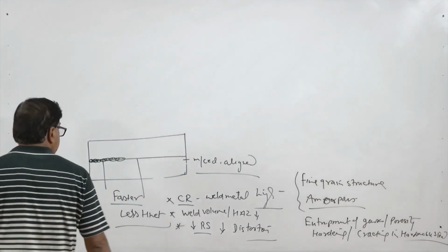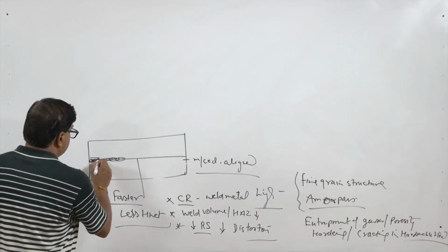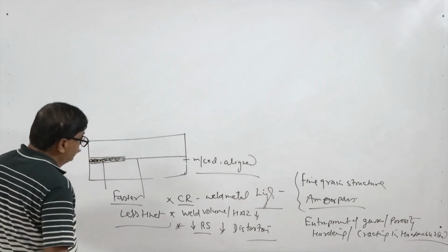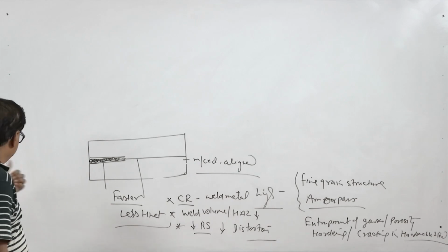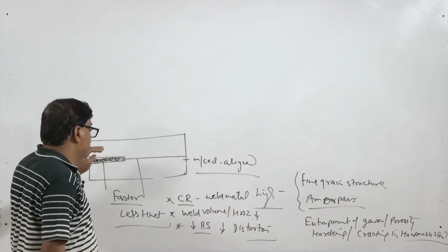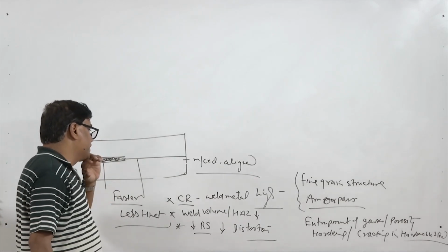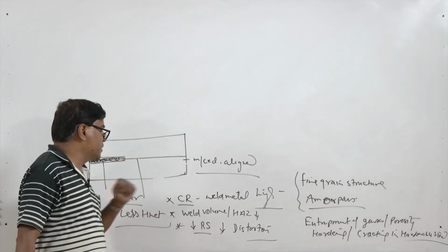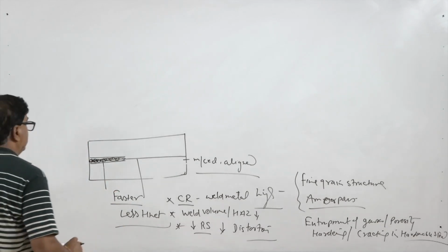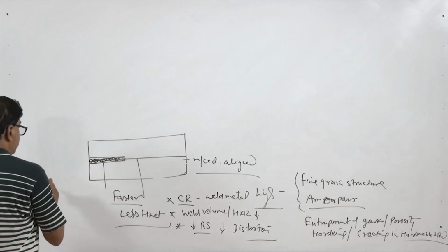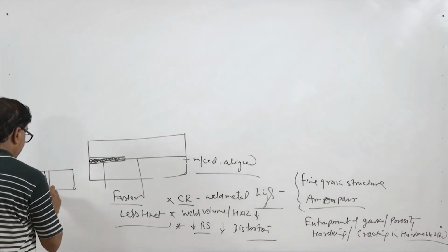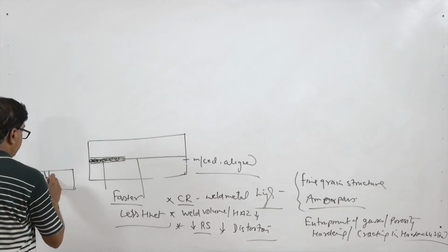Since the volume of the weld metal produced, and the heat affected zone produced in laser welding, is small due to the limited heat input needed for fusion, it results in reduced residual stresses as well as distortion tendency. Further, most joining in laser welding does not use an external filler, just the fusion of the faying surfaces is achieved.